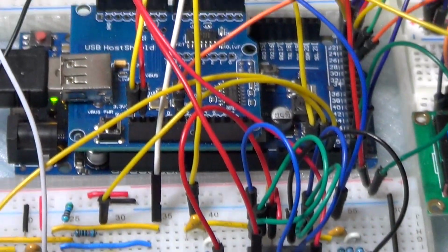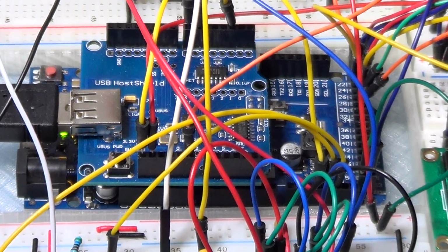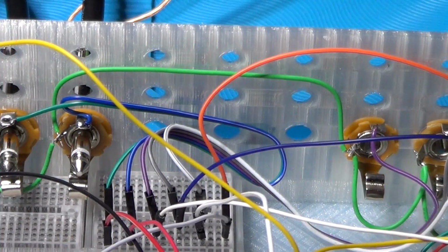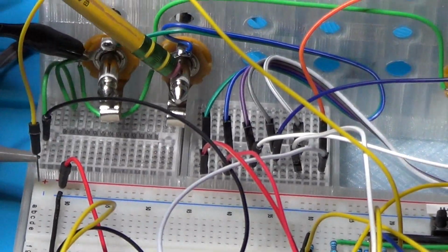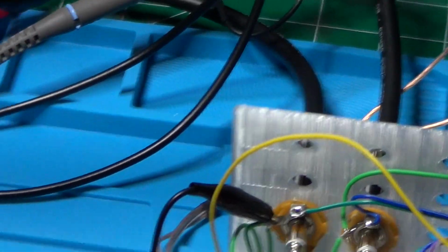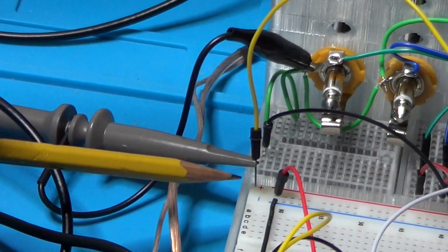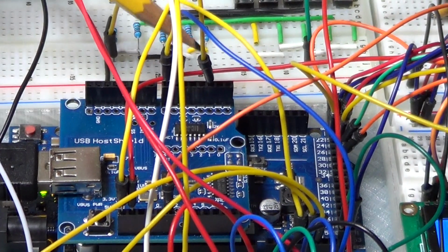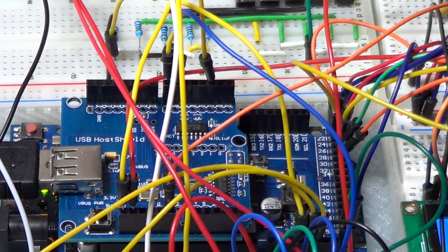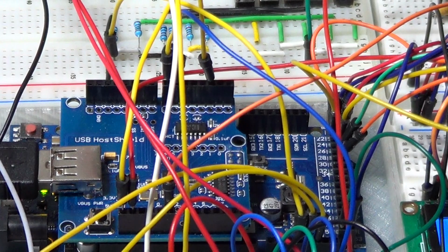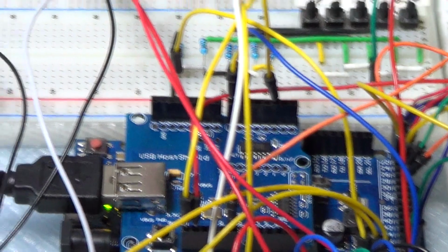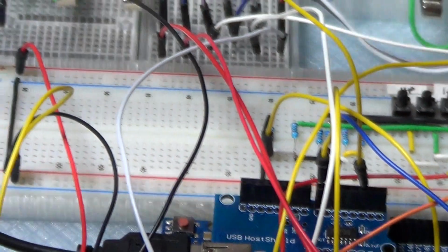Since I have only 2 complete filters and amplifiers, there are only 2 jack sockets on the prototype, right here. The socket on the right is connected to channel 2 of the oscilloscope, the one with the blue trace. The other channel of the oscilloscope, the one with the yellow trace instead, is directly connected to one of the ports of the Arduino, so we can watch the actual PWM output. You can see how the 3 pins I am using are occupied by the USB shield, but there is still access through the shield header.